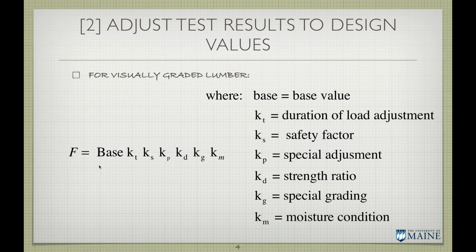So the strength of wood, you've got the clear values, time impacts things, and the safety factor, and this really ties in because not every two pieces are the same. Our results are variable. If everything was the same, then we wouldn't need it. So this really ties in with variability. This relates to a volume effect that we'll talk about. This refers to the amount of defects. This refers to density, and this refers to moisture. All of these factors impact the mechanical properties of lumber and solid wood.